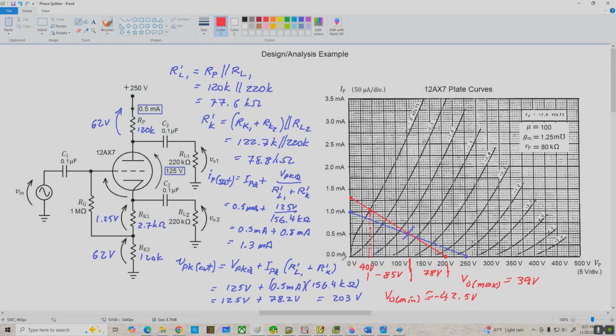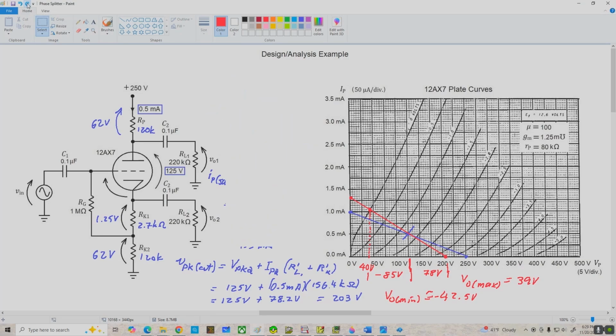So what we see here is an example of how you never get something for nothing. Since we're using this amplifier to effectively create two amplifiers, one inverting and one non-inverting, the sacrifice we have to make is that the output voltage swing for each half is divided by 2. Okay, now we're ready to do our small signal AC analysis. So let me clean off the workspace here and we'll get to it.